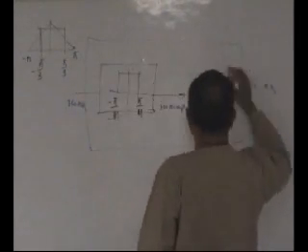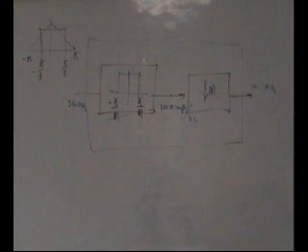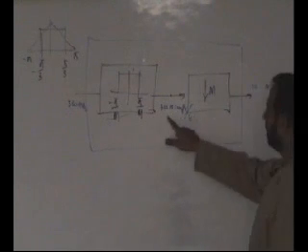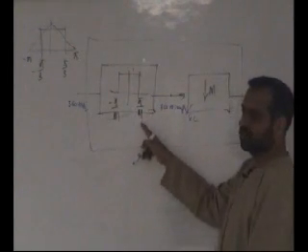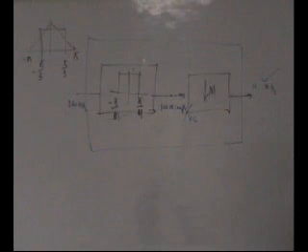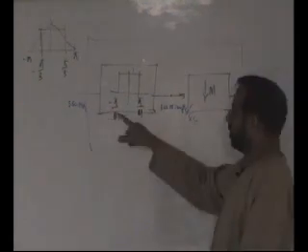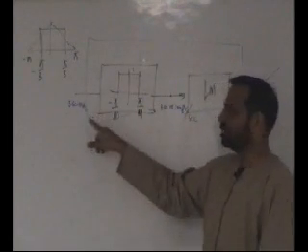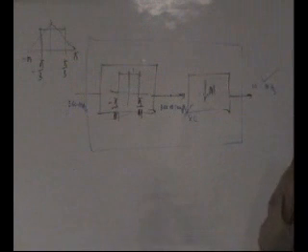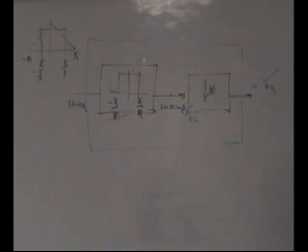Now people have tried to come up with an architecture where this whole thing is replaced by a design which, instead of working at 360 megahertz, works at 10 megahertz. Effectively you make a design where this is really the output rate. So you want all your filters, the convolution, to happen at this rate and not at that rate. Though the input data is coming at this rate, you want your design to work at the output rate.